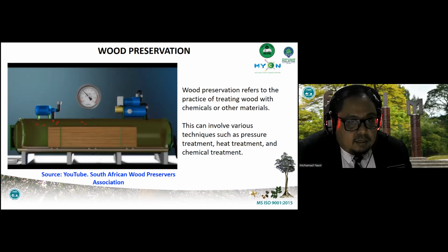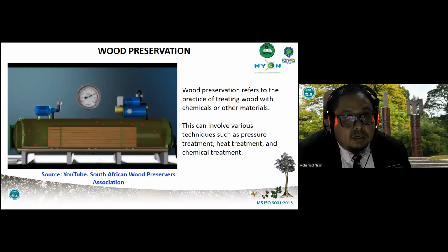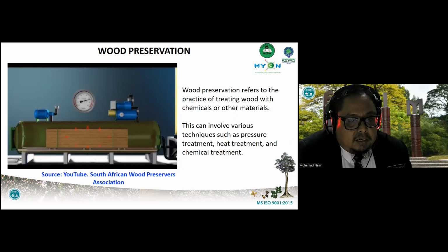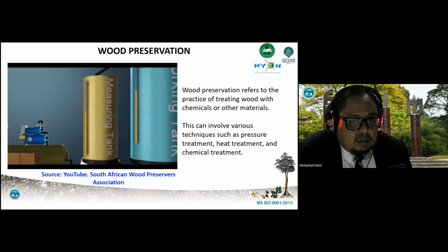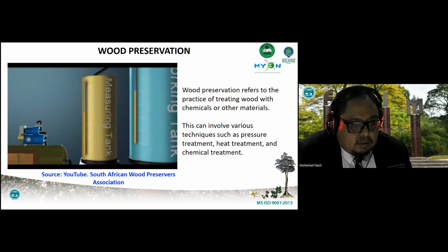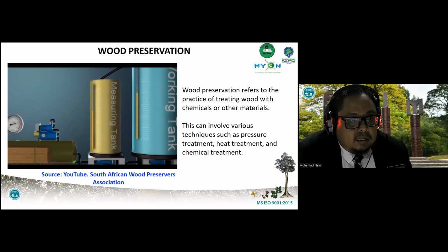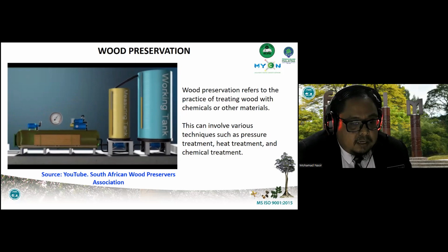Then the pressure is applied, usually at 200 psi for 2 hours. Then after the pressure is applied, the liquid will flow back into the tank.